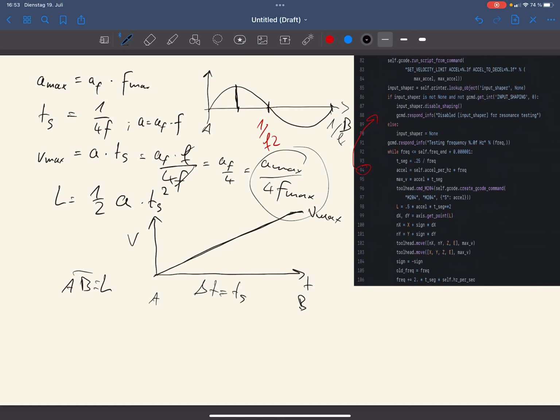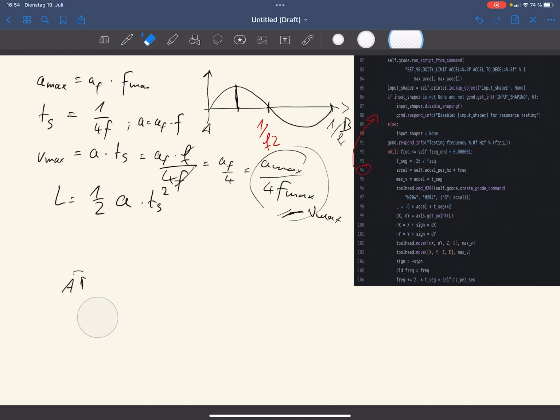So, of course, this is not how movement happens, because our kinematic system does not only accelerate, it also decelerates. So how does that one look then? And to reach the time, we also know that the time we need is 1/2f, not 1/4f. And I think that's where the mistake was made. I think whoever implemented that thought that he is just reaching half the speed on the way, so he takes double the time, but that's not true. So how would it actually look?